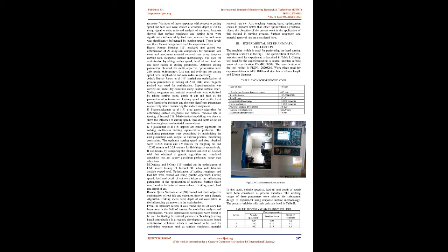Optimum cutting speed, feed, depth of cut and nose radius obtained were 160 m/min, 0.1 mm/rev, 0.2 mm, and 0.8 mm respectively. Cryogenic environment was found to reduce surface roughness, power consumption, and cutting force and increase tool life.